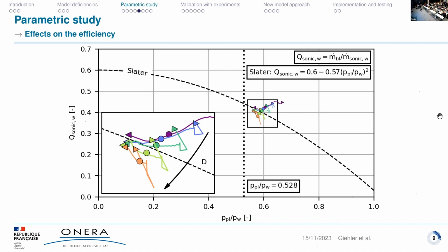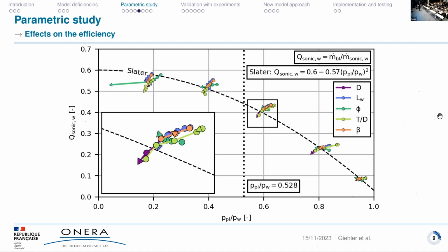So we see the trends are not always the same. We did it for different pressure ratios. And in the end, we get a trend for just the mean values that the bigger the hole diameter, the lower is the mass flow rate we can remove, and the higher are the pressure drops. Since we have a higher flow momentum of the captured flow, we also have higher losses because we have the barrier shocks and the underexpanded fans, jets inside the cavity. And this is done now for all the different parameters.